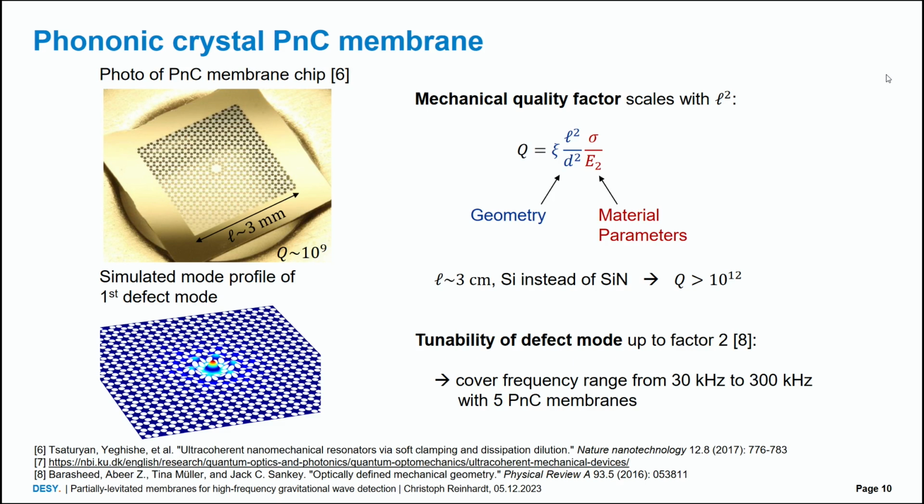Yeah, this is true, of course, but there are many ways to deal with it. You can change the frequency with the mode shape, you can change it with the size, you can change it with the stress level in the nitride. So there are definitely a lot of parameters you can tune in order to get to this regime where you're clearly dominated by the optical spring.